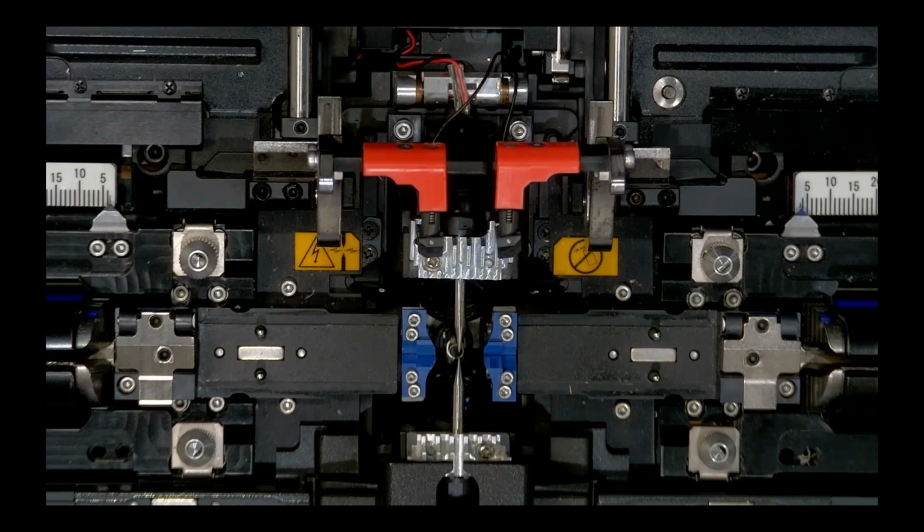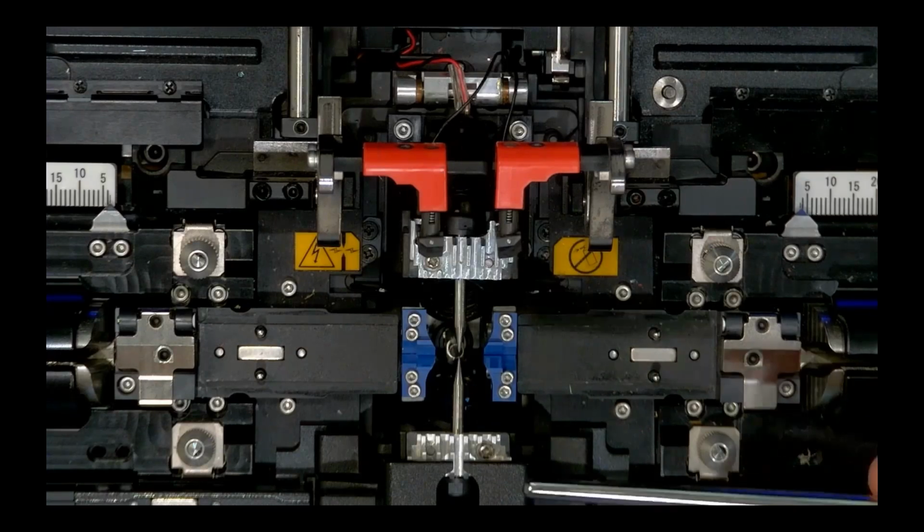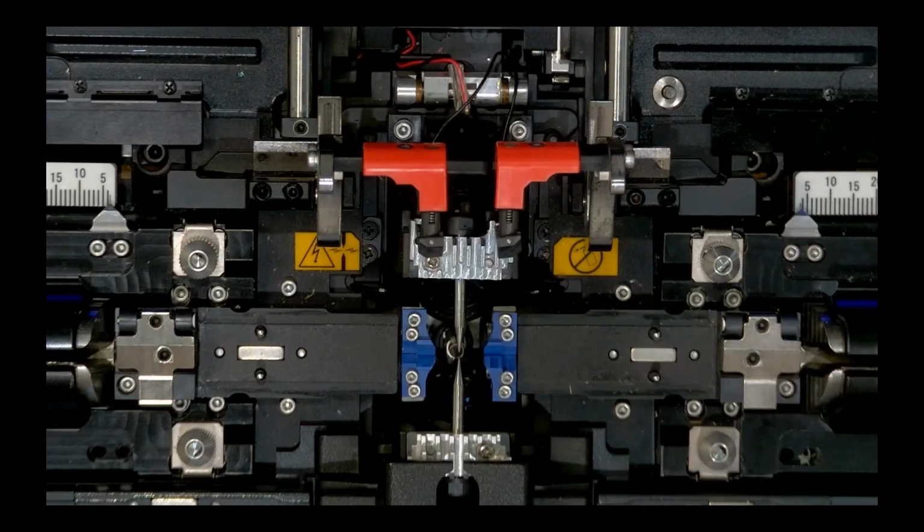But in many cases, this can also be used for verification. Maybe you have a specific fiber that you don't know exactly what kind of PM fiber it is. Someone may say it's a Panda fiber, but you just want to double check to be sure. So you can put your Panda fiber in here and verify, okay, yes, this is a Panda fiber.